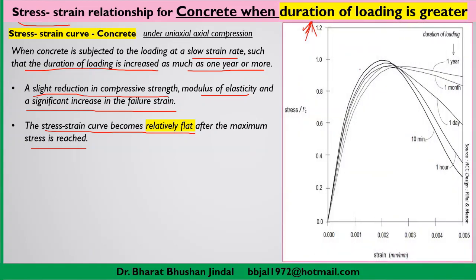Now, in this diagram, you will be able to understand along y-axis there is stress, along x-axis there is strain. Now, different types of curves you are able to see. Very first curve is when the loading is applied just for a 10-minute duration, which we have already discussed in the previous graph. Now, if you increase the duration of loading, it may be 1 hour, then 1 day, 1 month, 1 year, you will be finding that this curve is getting somewhat flat.